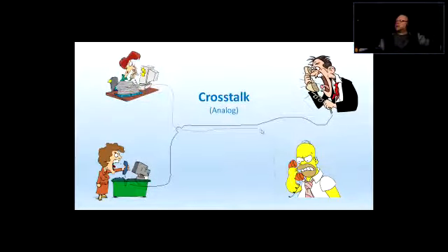And some of the wires are passing at some point, those lines or those pairs are in close proximity to one another. What would normally happen, by means of induction, is that one line could be affected by the other. We're talking about something that we can call a bleed through. The signal can bleed, it's bleeding from one pair to another.